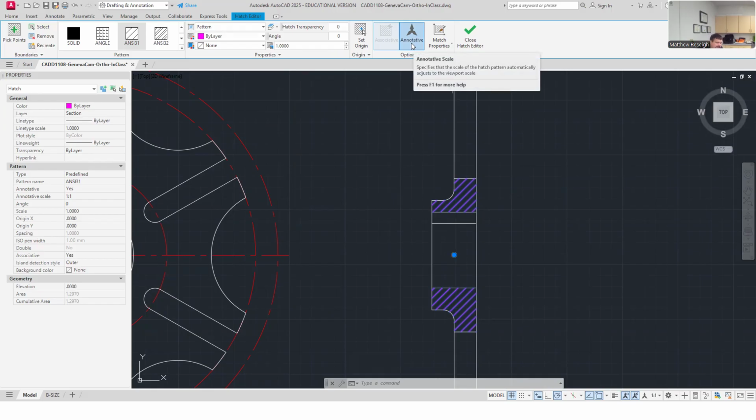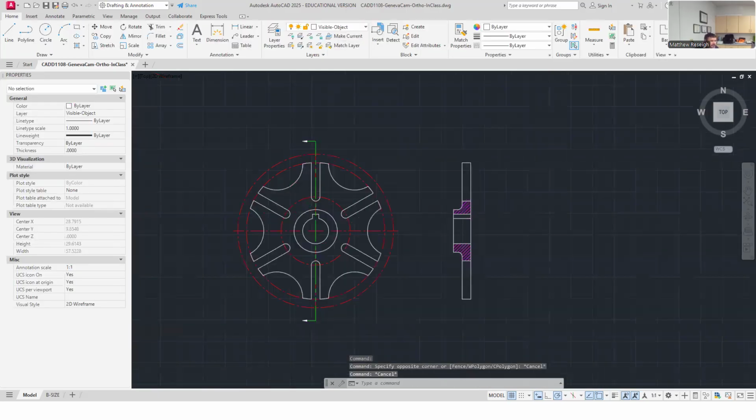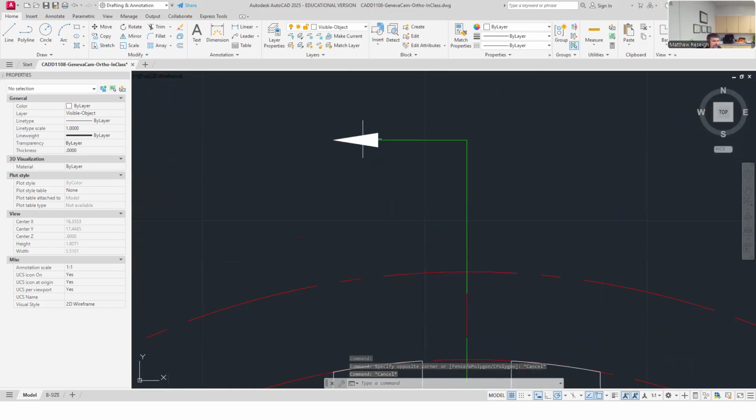that your text does. This hatching can, if you jump out and scale your drawing, become just an ugly mass if the hatching stays really tight and small, and it won't even look like hatching. And then if I go big, I might see the grid. Anyway, it'll adjust size wise so that you can clearly tell that it's a hatched area. So I like to make it annotative for that reason because I don't know what my scale is going to be. We sat there and beat ourselves up a little bit about this.